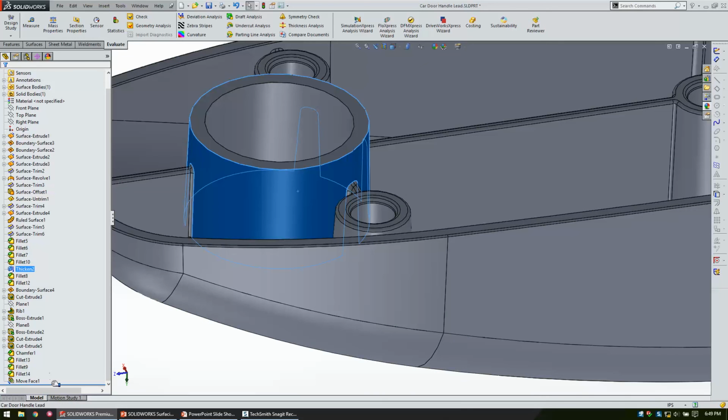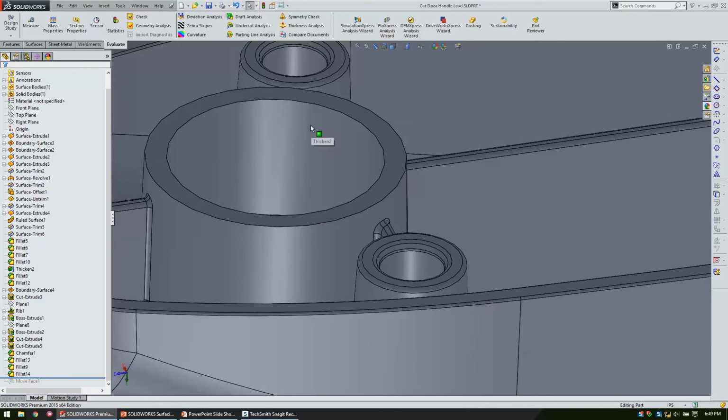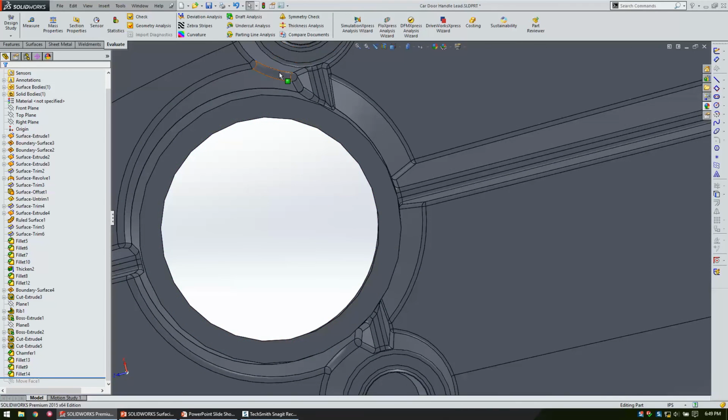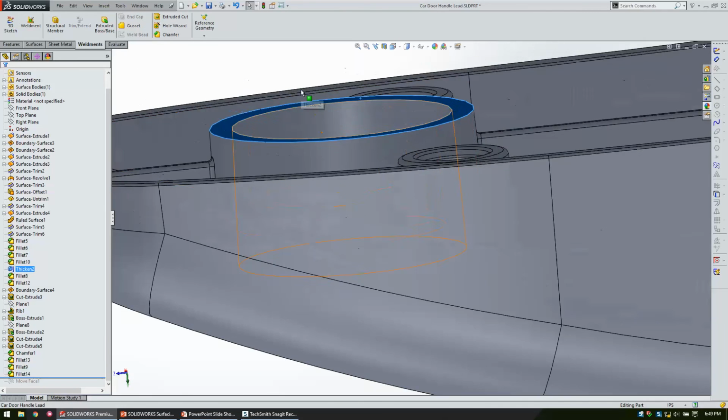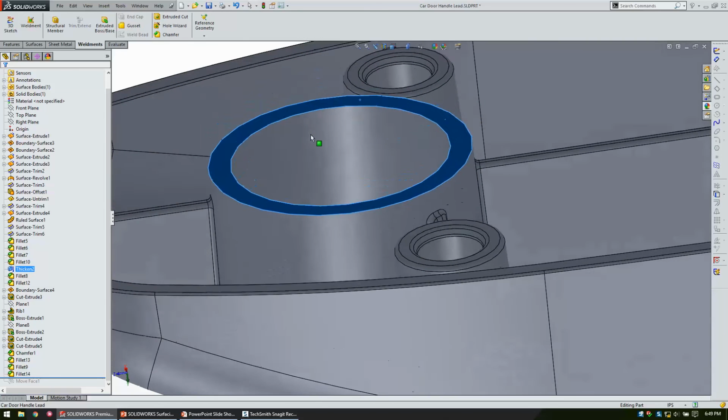Because this is why I love this model, but because this is tapered both directions for draw, it'd be very difficult. I need this face like an 1/8 inch taller. This would be very difficult to pull off with 3D geometry because I'd have to extrude with draft and then cut with draft, or delete and trim and do a bunch of weird stuff.